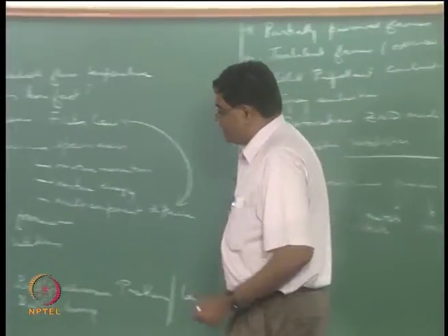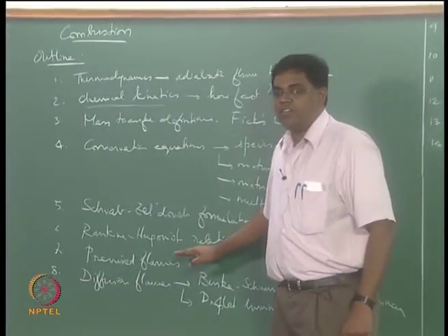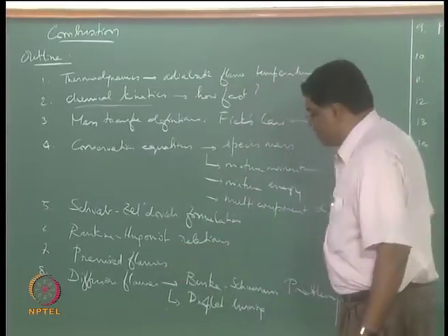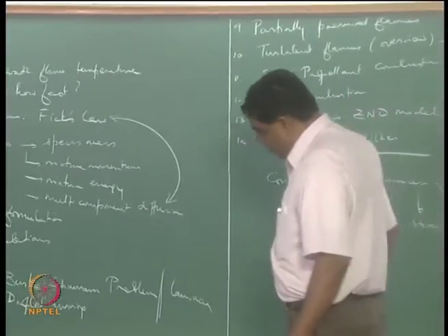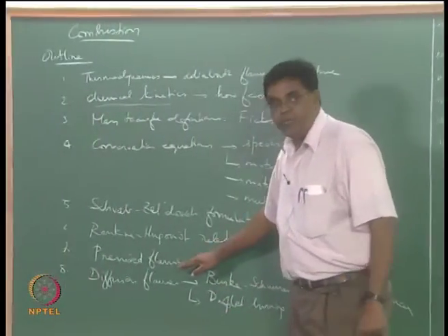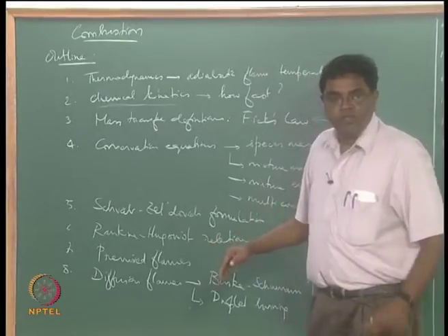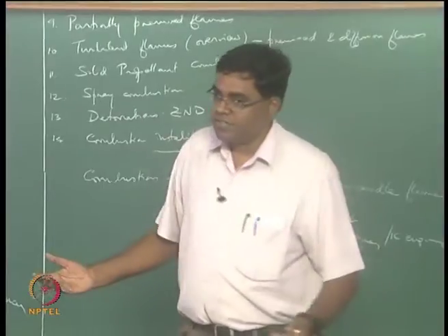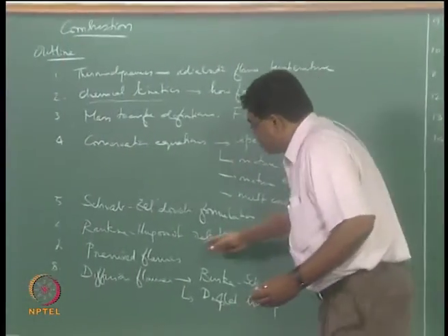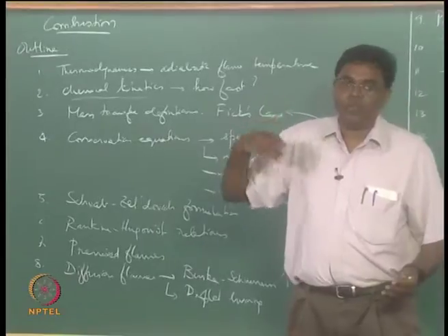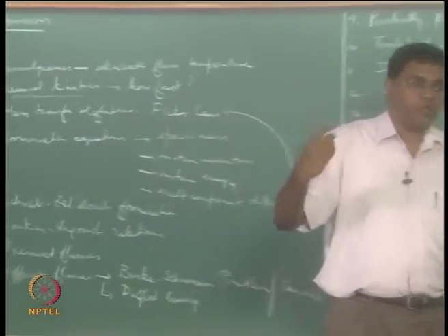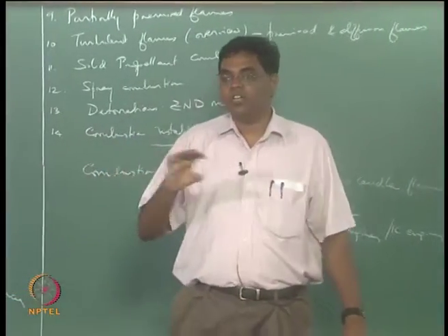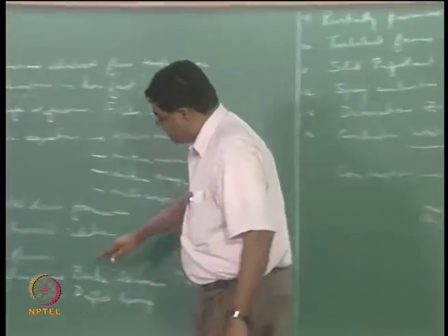And we will find that at the end of it it's not possible to avoid getting into the flame, and therefore we will get into the premix flames. We will spend quite a bit of time doing this. We'll try to find the laminar flame speed, and then we will look at flame stabilization issues, flammability limits, ignition and quenching, all these kinds of things over there. How to treat flames globally when given a flame speed, and how the flame speed should be computed in the first place, flame shapes versus flame structure, and so on. So I would like to distinguish these things as we go along.